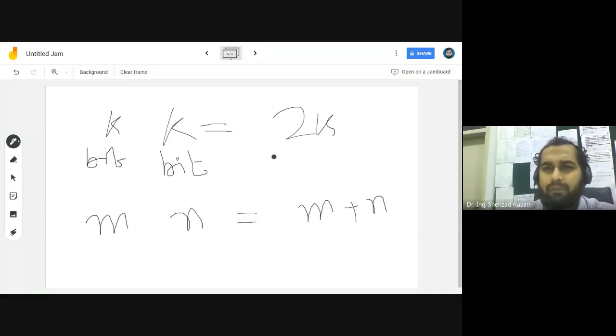But to keep it simple and regular, and regularity is an important property when you design anything, regularity means that if you have selected a number, all of the registers should match that number, or a multiple of that number. It can't be that you have a different number of bits for multiplicand and multiplier, because that's going to complicate the whole design.